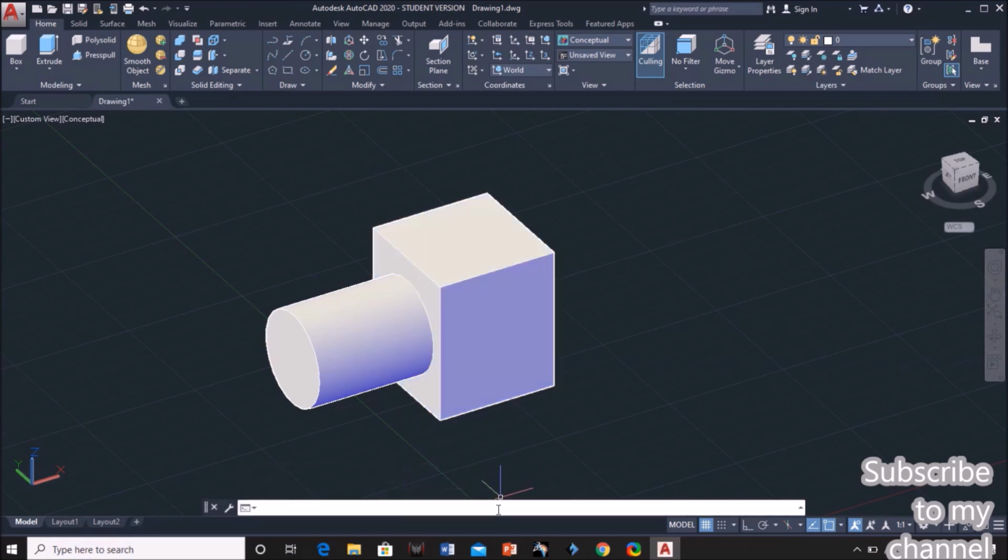Again give the command as circle, C, enter, and specify the center point as we did previously. Set the midpoint here. Just move the cursor in this direction, we'll get the green dotted lines, so that is the midpoint. And again on this edge, set the midpoint and move the cursor in this direction. This is the center point of these two midpoints. Just click the center point and specify the radius. I am giving the radius as 15, enter. So the diameter is 30, and the circle is drawn.